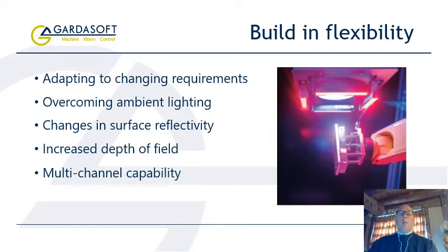Another common example is where an established system becomes adversely affected by ambient or other light sources. If the light is already running at its maximum rating in continuous mode, then pulsed mode Overdrive offers scope to increase brightness further and overcome the light interference. A combination of increased brightness and either reduced camera exposure or reduced aperture size can significantly reduce ambient light interference.